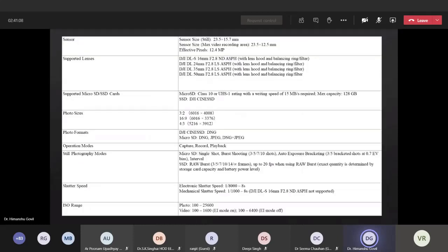These are the specifications they have, and these are the formats which you receive, particularly when you are flying in these areas. For the photo size, you can also define the overlaps. In general, in photogrammetry we used to go for 60-40, but these systems allow us to go for 90-10 also. It means you can get coverage of 90% of the second scene.